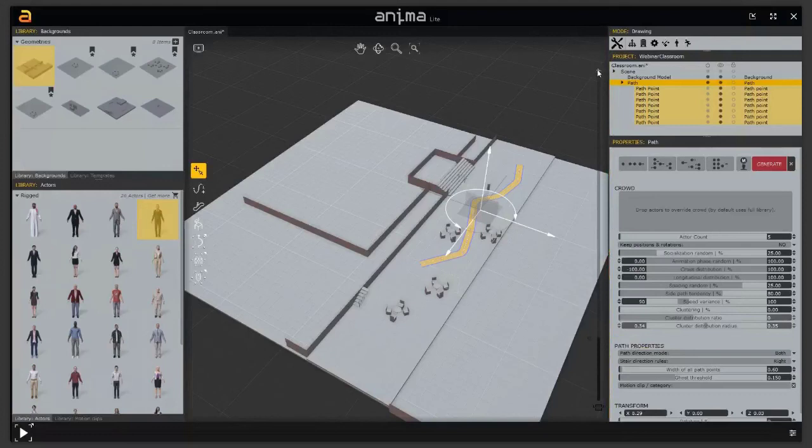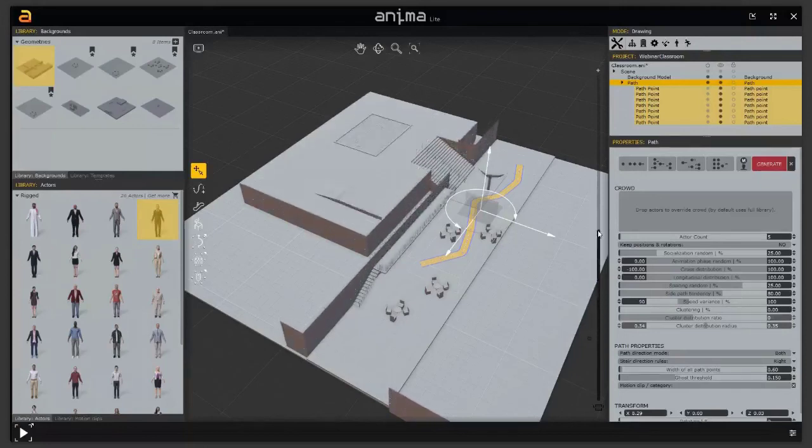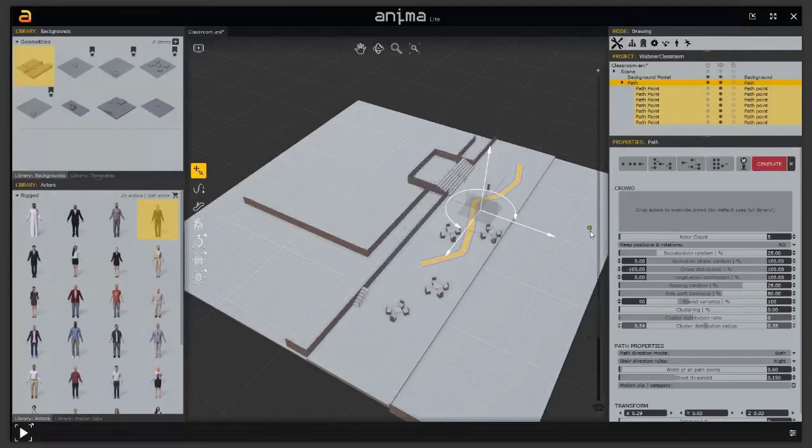Now we can do this also by using this plus button at the top of this vertical bar, but I usually prefer the right mouse button, okay? Now, what we can do is, for example, create another bookmark here when we want to work on this other floor. This could be another area, okay? So right click, add point at current height. So we can simply, by clicking on these dots, switch between one section and another.